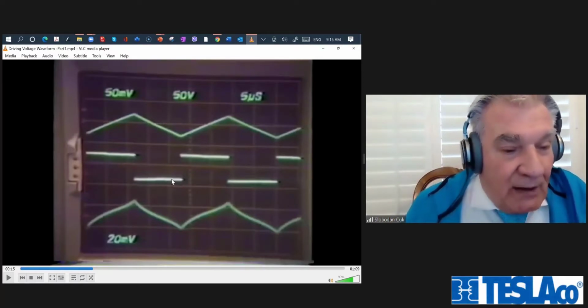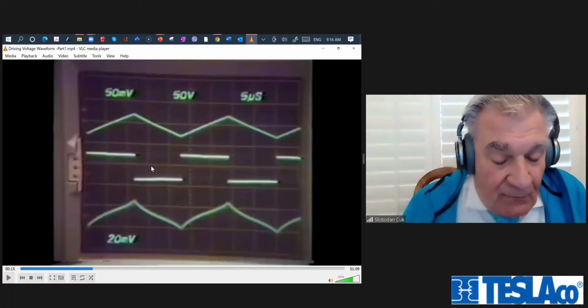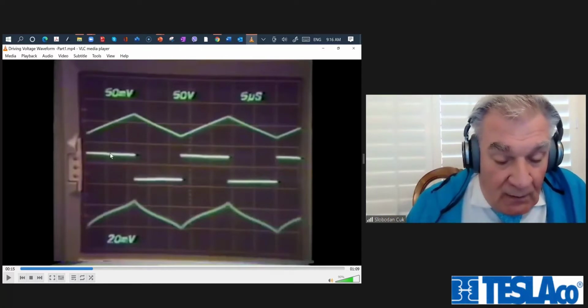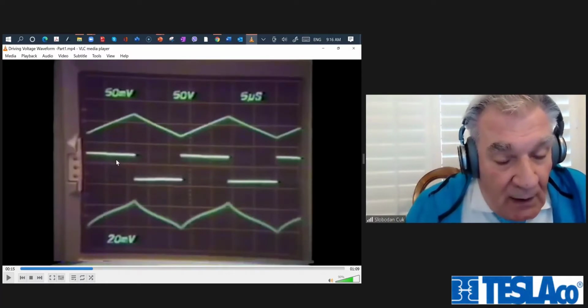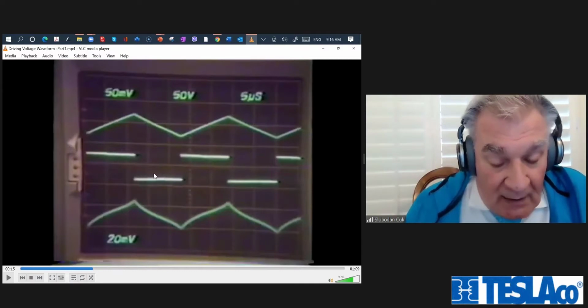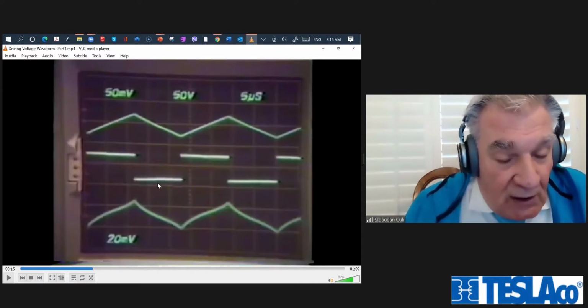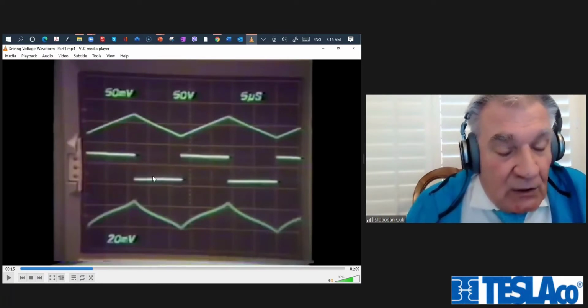And that is not happening with most of these other transformers, which are now claimed to be called transformers, but they don't do that. For example, the forward converter, and the flyback stores all the energy and things like that. Anyway, the point is, this is square wave voltage drive, so that means you have to make a switching converter such that its transformer, if it is square wave, and especially if it is not square wave rectangular drive, has a flux balance. And also you have to make sure that it has a charge balance, which is automatic in a 60 hertz transformer, but in a switching converter, no.